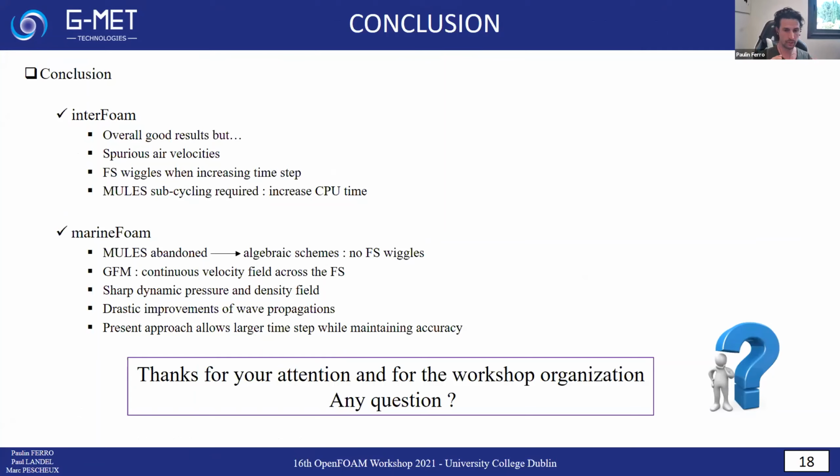You need to determine where your free surface is, which is well described in the paper of Vukčević, and based on that, you modify the extrapolation on both sides of the interface in order to modify how you compute the pressure. This leads to a modification of the Laplacian and gradient operators, both Gauss gradient and least squares gradients.